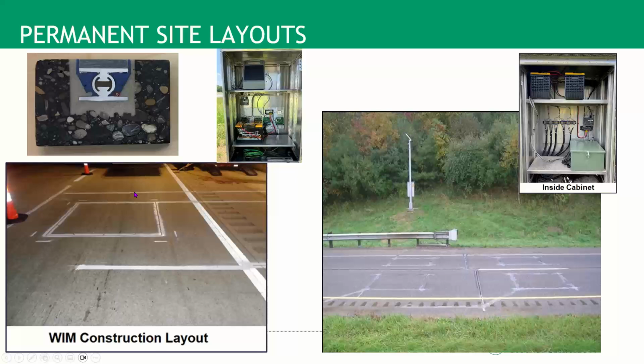This is how it's laid out with a template. This is before we actually installed it. So this will be a piezo, a special kind of piezo. It's made of quartz. This is a cross section of what it looks like. These are our weigh in motion sensors that we have. We're within 80 pounds, with people going 75, 80 miles an hour, obviously over the speed limit on the freeway, and we're that accurate.